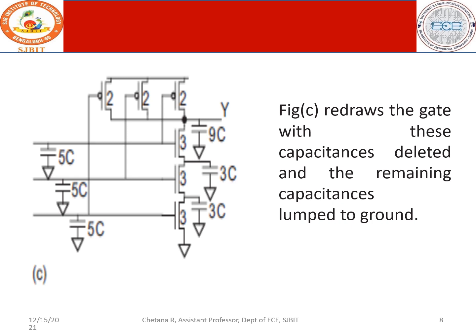The drain capacitance of the PMOS together, the lump of this is 6, and the drain capacitance of this particular transistor is 3C, and this was 2C, this was 2C. So together they combine, this was also 2C, and they form 6C. This gives you 6C plus the 3C of the drain capacitance here. That is why we have it as 9C. Only the top NMOS transistor will have this capacitance 9C, the rest will all remain as 3C.